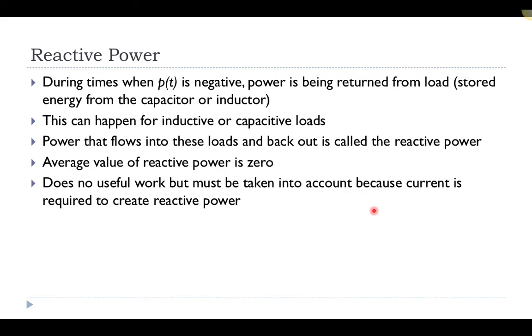On the other hand, you have reactive powers. During the times when the power at a particular instant in time is negative, that means that power is being returned from the load. It was stored in the capacitor or the inductor, and then it can be returned back again. So this is kind of like opening and closing a switch in DC. You charge a capacitor, it's fully charged, and then you switch the switch so that it can discharge. It stores that energy, and then it can release that energy.